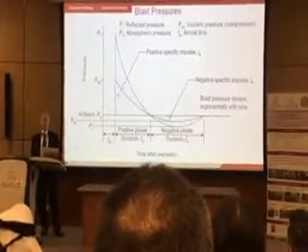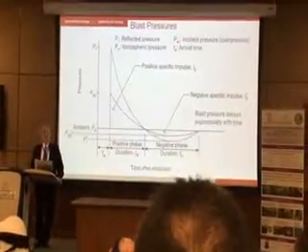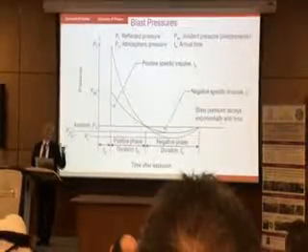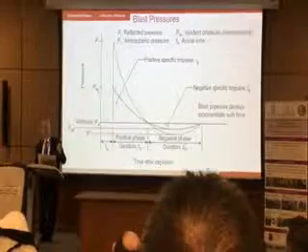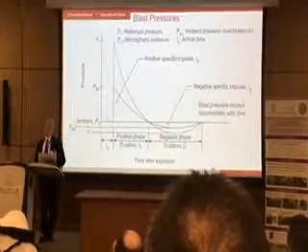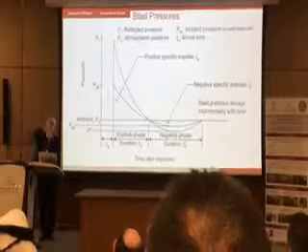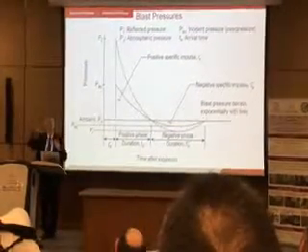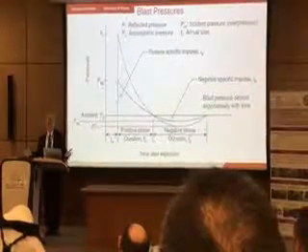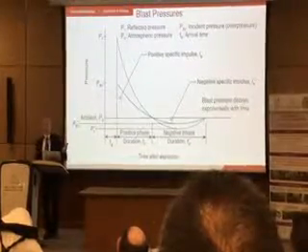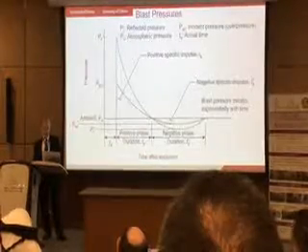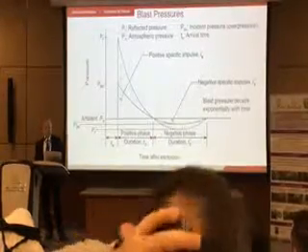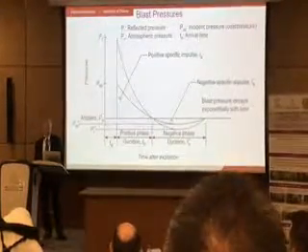This is the pressure-time relationship. Of course, in structural engineering, we work with dead loads, live loads, wind loads, seismic loads. When it comes to blast, this is our load. We need to specify pressure versus time. It's a dynamic load, so if you hit an object, there's a time over which it changes, so it's a function of time. And when we do dynamic analysis, we have to use this pressure-time relationship. Here, the solid line indicates incident pressure, and the dashed line is reflected pressure.